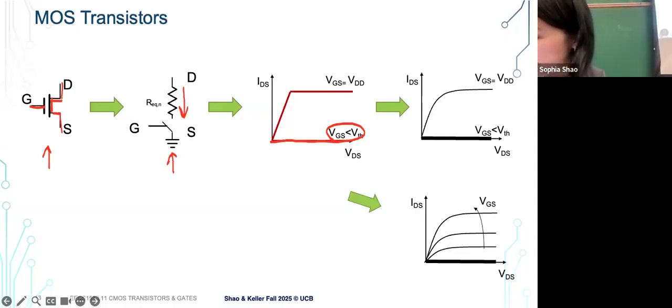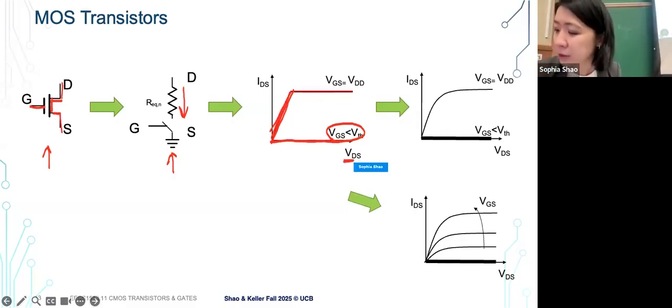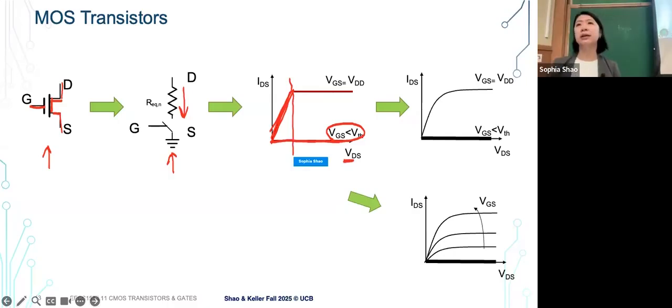But when we have the gate voltage applied, the channel is conducting, and this linear region basically acts as a resistor until the drain voltage gets close enough to the gate voltage, and that gets to the saturation region, right? So those are the 3 different behaviors when we think about a transistor.